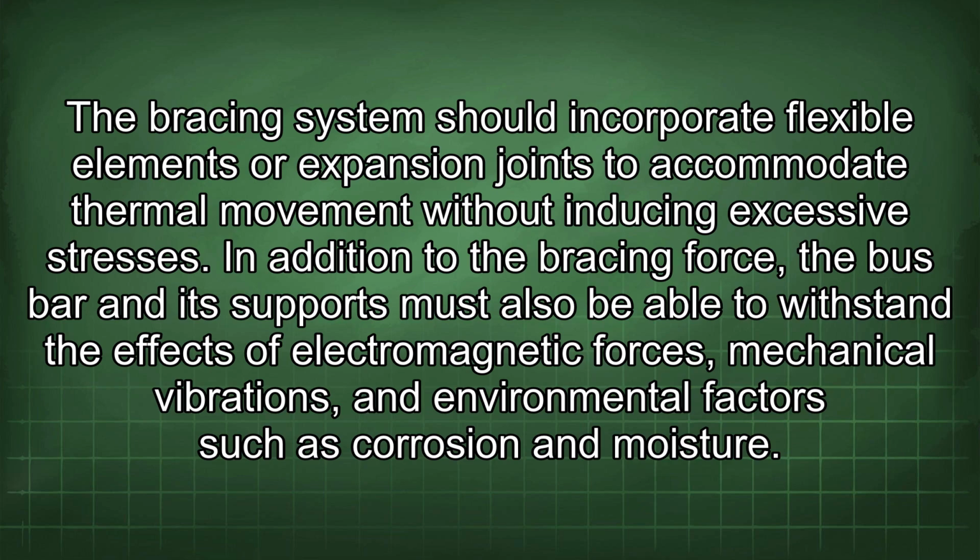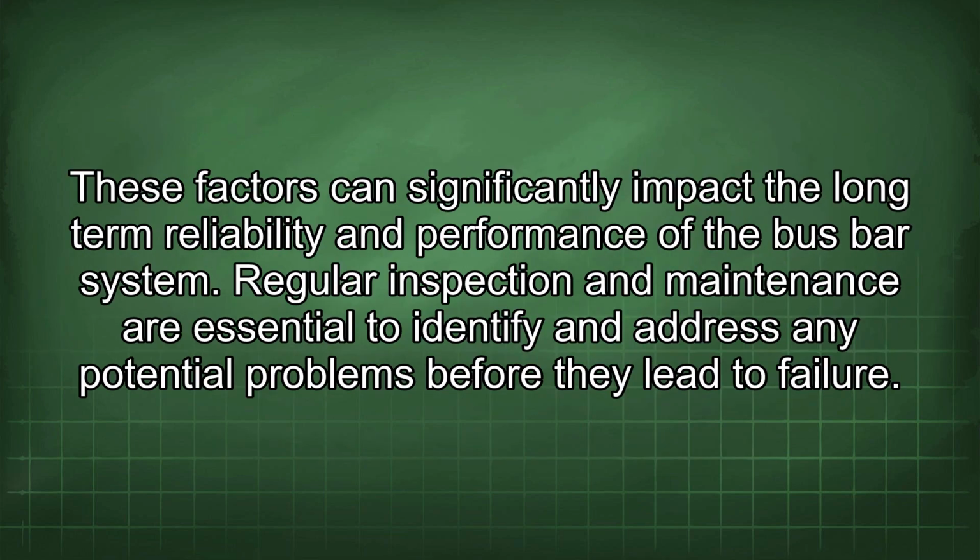In addition to the bracing force, the bus bar and its supports must also be able to withstand the effects of electromagnetic forces, mechanical vibrations, and environmental factors such as corrosion and moisture. These factors can significantly impact the long-term reliability and performance of the bus bar system. Regular inspection and maintenance are essential to identify and address any potential problems before they lead to failure.